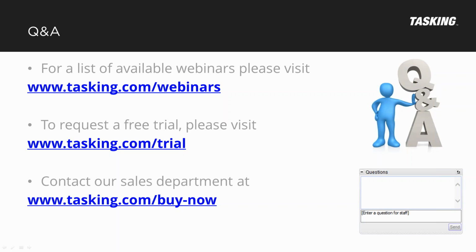There was another question. Can I use object files generated by HiTech and application by tasking? As I said, no, it's not possible because, for example, this specific vendor uses a different set of registers, address registers and parameter passing than tasking does. So they are not compatible. Even if they stick to the same EABI, this EABI leaves some open space for the vendors to specify, and these address registers are, for example, different. So it's not possible, no.